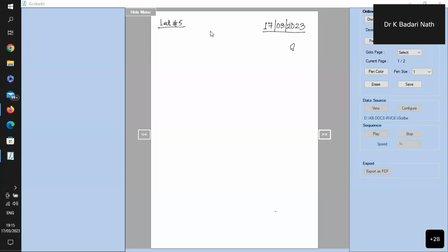Continuing from yesterday, we discussed in the last class how we can transfer the data between two registers, and what sequence of instructions we are supposed to give from the control unit so that efficient transfer can happen from one register to another register. After that, we understood how a complete arithmetic operation like addition can be performed, which involves two operands in the registers and storing the answer back into one of the registers. That required 3 clock cycles, or 3 steps.